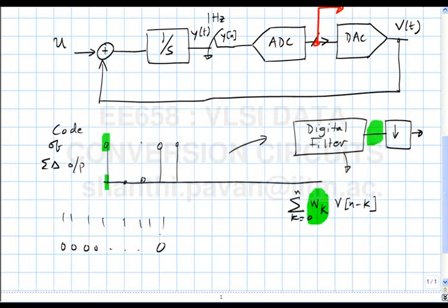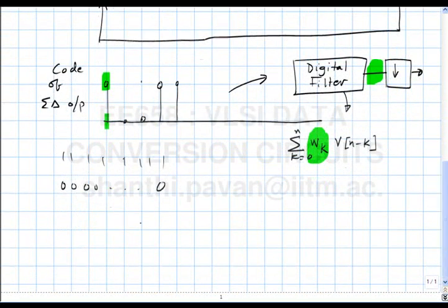Yes. So once you average out these numbers, then you will get it, so this is very simple. I showed you this earlier, where I took simply a coarsely quantized input and passed it through a smoothing filter. A very low pass filter, which cuts off all the high frequency components of the noise.